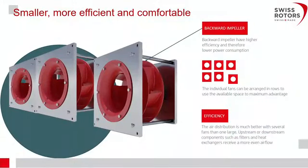So what is in our fans? We have backward curved impellers, which give much smoother operation of the fan in characteristics. Individual fans can be arranged in one row, two rows, or three rows, installed in the diaphragm of the air handling units, connected to each other and controlled by one controller.